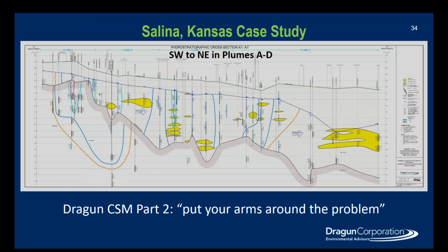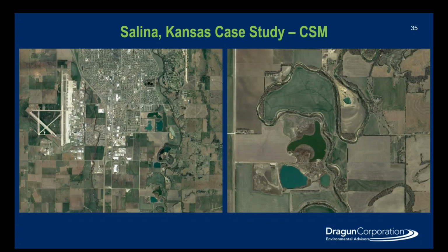So this is generally what we saw in the southwest to northeast direction. We saw mostly clayey soil in the overburden that varied between a few feet and 80 feet or so. We found sandy soil. The sandy parts were very sporadic and disconnected in the southwest, but got more connected going to the northeast. We found the bedrock, and we found the water table was fairly close to the surface, but got deeper as you went to the northeast. And we found contamination in the bedrock.